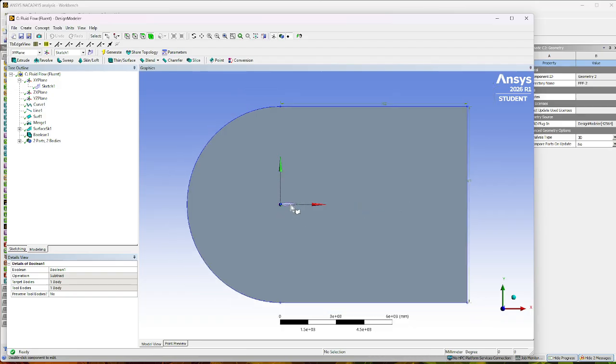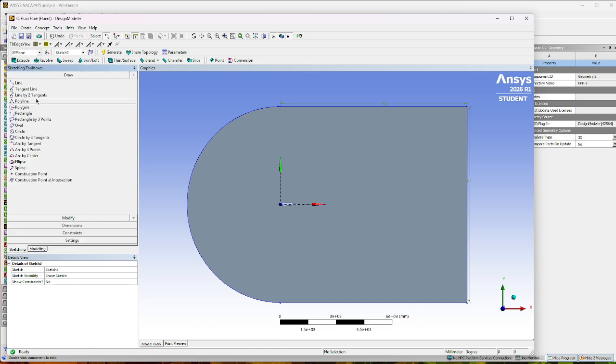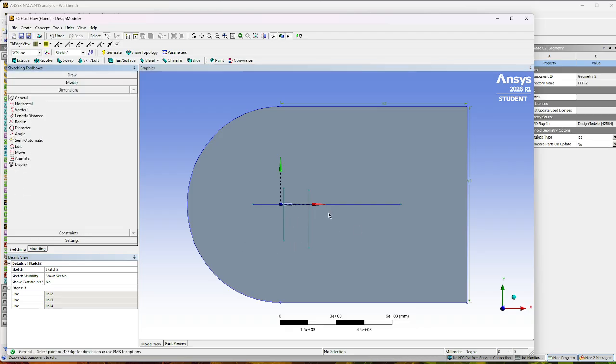So now that we have this merged, and the one surface made, we're gonna go ahead and create another sketch. So up here, create another sketch, and then we're gonna make some lines. So we're gonna make a line here that's intersecting a part of the airfoil, like that. We're gonna create another line over here, vertical, and then we're gonna make a line that's gonna be on the x-axis. So here, here, there we go. And so we're gonna dimension this line here.